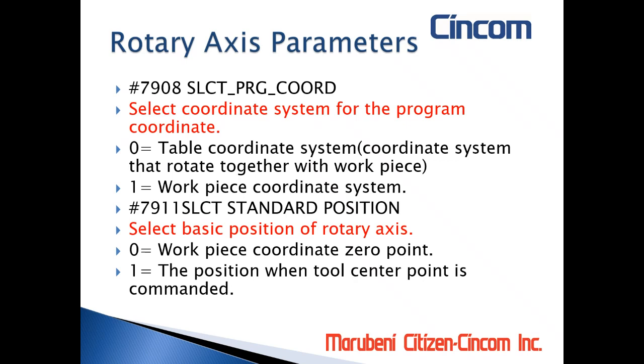I will call up a funny move, and I'm thinking more like a table machine or a milling machine. It will swing the whole tool around the part, so you will break that tool so easily and probably crash the machine. So be aware. It needs to be on specific settings in combination with the software.